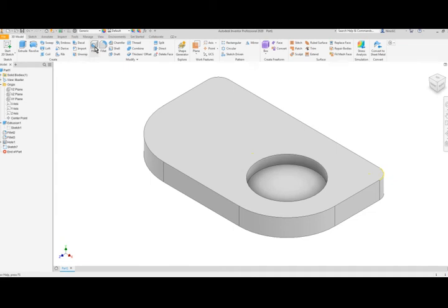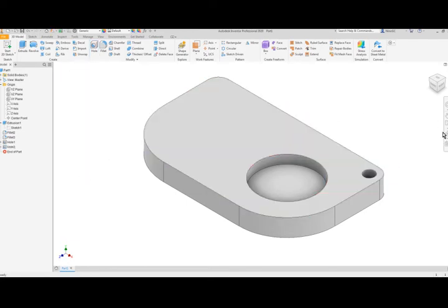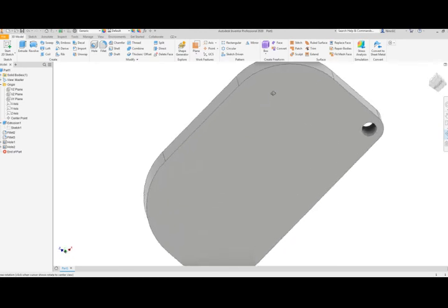and then I click on hole, I can actually take and then select that center point, and it will create the hole. In this case it is way too big, so we'll just reduce it in size. And because it's attached to the center of the fillet, it is automatically concentric with the fillet edge itself. I can indicate, in this case, how big that hole is going to be. So I'll make it, say, 3 millimeters. And then once again, I will, in this case, say OK, and it drills the hole all the way through the plate.